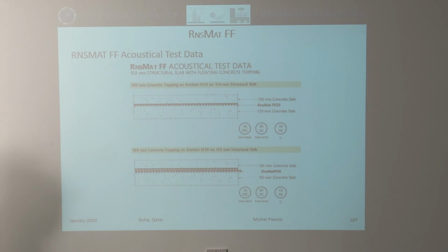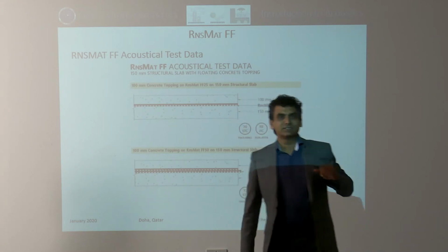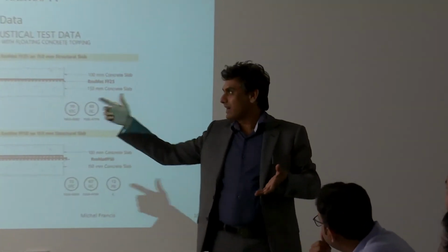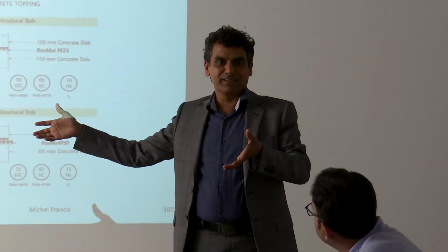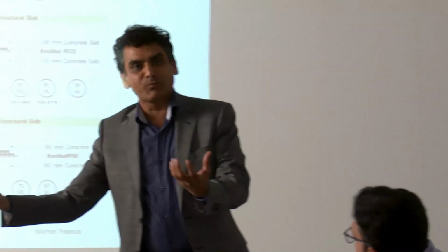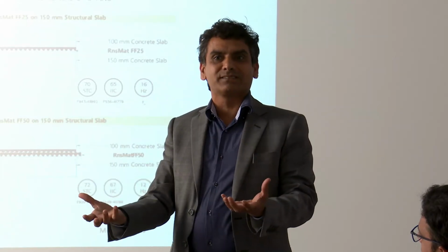This is the point. If you propose only under the machine, it's for vibration. As he asked, if this is the room and the equipment is occupying only half of the room, then does the whole room have to be covered or only that machine area? Very good question, am I right? Very, very good question. Okay, fine. Now, I need to understand the weight of the equipment. As rightly we've been discussing, where are the point loads? Are those point loads having any base or not? If no base, then give them a base with isolators.